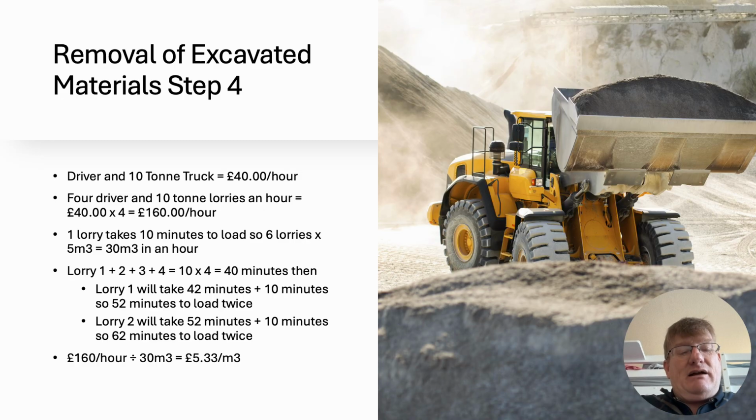That's how much we're taking, 30 metres cubed. It takes us about an hour, 30 minutes, for 30 metres cubed. So we're costing £160 an hour. All we do is divide that total hour by the quantity, which gives £5.33. So in effect, it's £5.33 per metre cubed.